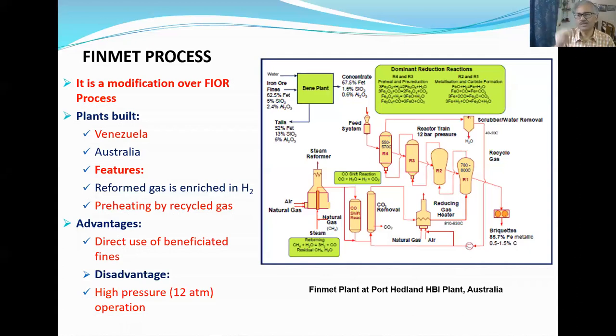If you don't have a high pressure, then whatever gas you are giving will form a slug and go away. There will not be intimate contact between the gas and solid. It's not easy. It's not very easy to fluidize the fines. So you require a very high pressure, and that is the bottleneck for the fluidized bed reactor. In most cases, in spite of very excellent modification in the process, this process did not survive. Just like Finmet also did not survive too much.